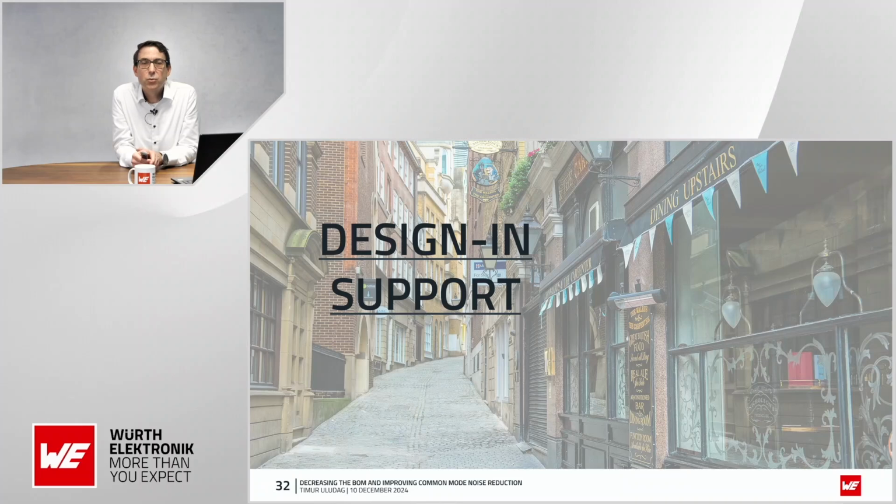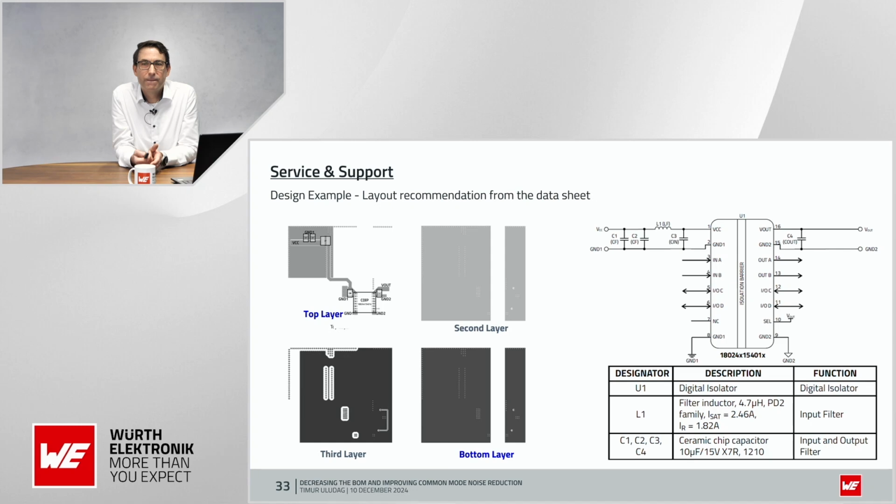That means we provide here in our data sheet or in the online catalog layouts you can take, you can follow, and then if you do the layouts like we show it here, or if you make the download for the power module and go for the design example, then it is easily manageable that you put it in your Altium design and have exactly the layout you need to pass the EMI, and also with the right stitching capacitor configuration.